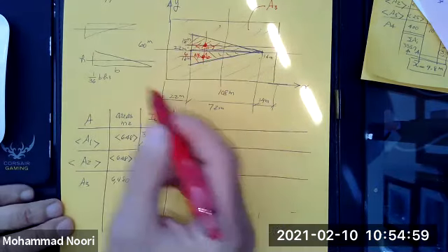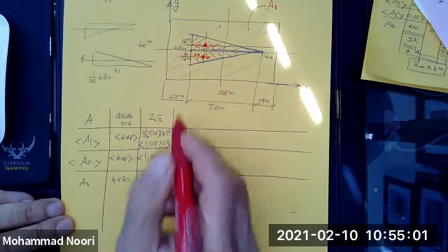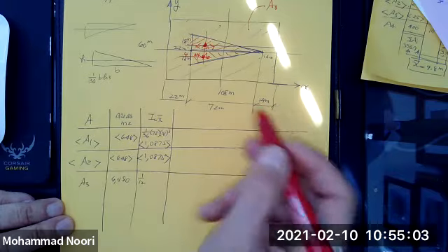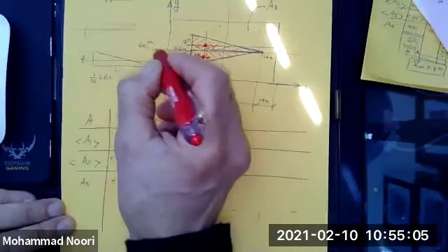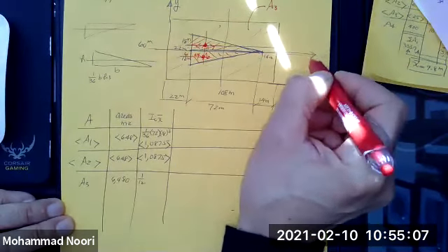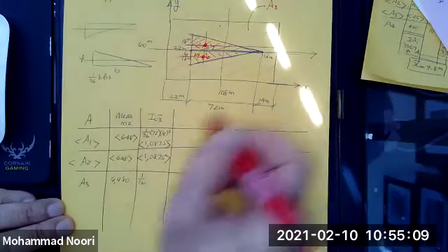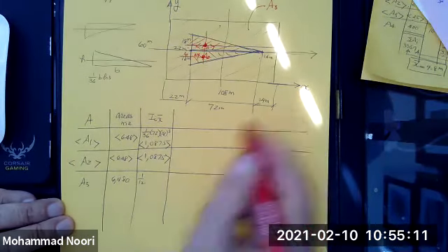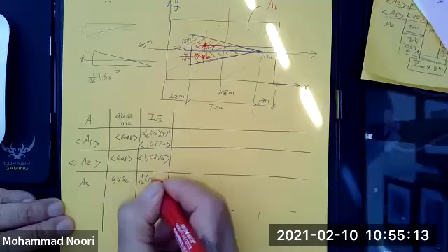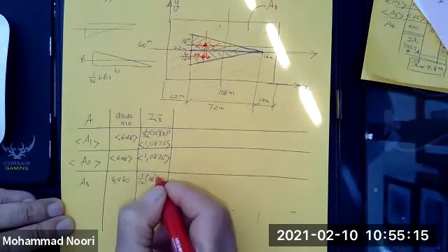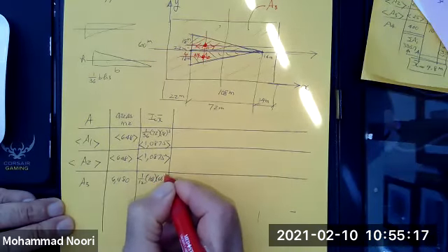It is a rectangle, 1/12 of base. So you're finding the moment of inertia about this axis for this one: 1/12 of base, which is 108, times height cubed, 60 cubed.